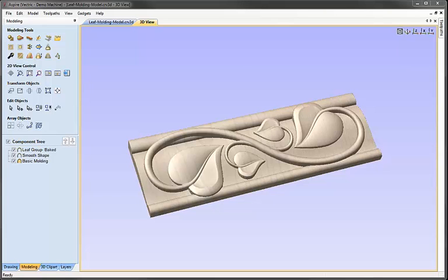Finally, we looked at how we could add the leaf decoration to a moulding profile without the creases being transmitted through the design. To do this, we sketched a new cross-section using the vector drawing tools that was a smoother version but still roughly corresponded to the shape of the original one. We then created a new 2-rail sweep, swept shape, and then cropped that back to the outline of the leaf and used that as an underlying shape for the leaf to sit on top of, so that when we merged in the original moulding profile, the part looked correct.